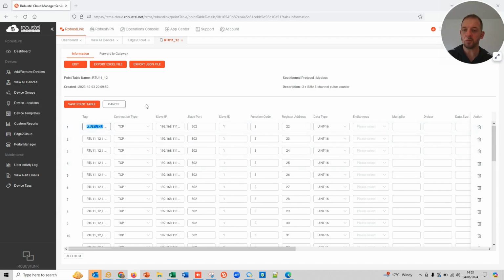And so we put together those two 16-bit counts to make one large 32-bit counter and just handle a little bit of rollover. If we get up to 4.5 billion or whatever 2 to the 32 is, we handle that at the application layer.